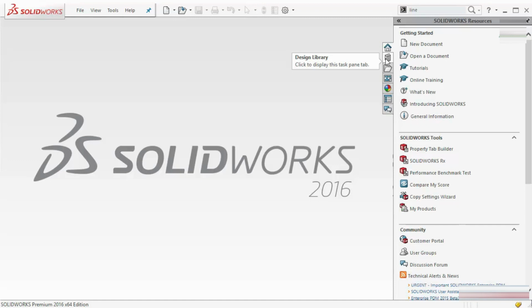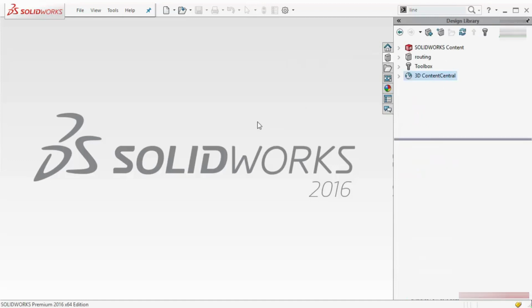The next tab, which is really very important, is the design library. Library means any part or anything you want to reuse. You can reuse any routing part from here, or if you want to reuse any hardware related thing, for example nut, bolt, washer, something like that, in that case you have to use this toolbox. You can set up your own toolbox if you want. This is highly customizable. Also, if you want to access 3D Content Central, you can do that from here. If you want to create a new library, you can also do that by using this option.